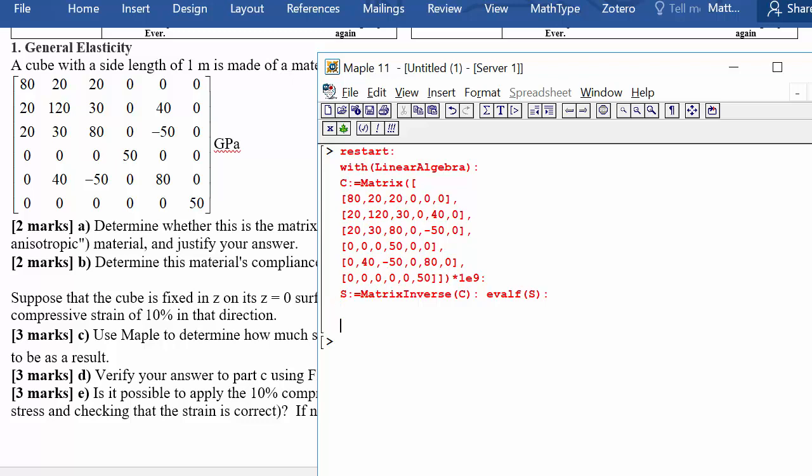then we can write out our state equation that we would like. So we know that most of the stresses are 0. So maybe it makes more sense to work with the compliance matrix this time. So we can say epsilon is equal to S dot the stress vector. So the stress vector would be sigma, and maybe we'll first say sigma is equal to vector sz. Sz goes in the third component. So 0, 0, sz, 0, 0, 0.